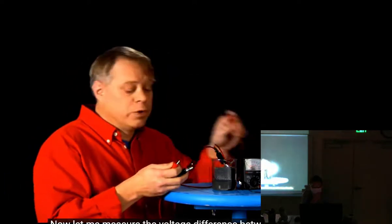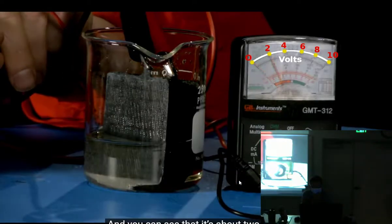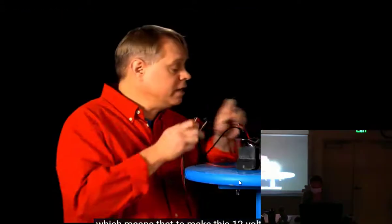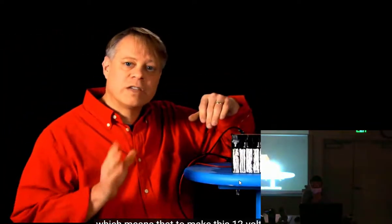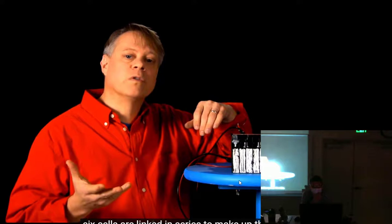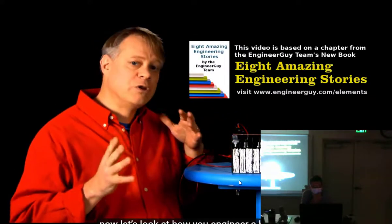Now, let me measure the voltage difference between the 2 leads. And you can see that it's about 2 volts, which means that to make this 12-volt battery, 6 cells are linked in series to make up the 12 volts. So that's the basic electrochemical reaction. Now let's look at how you engineer a battery.